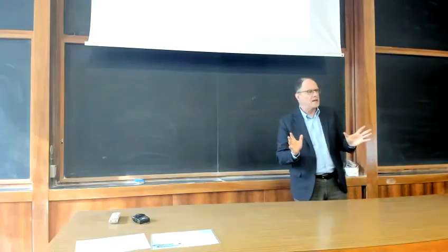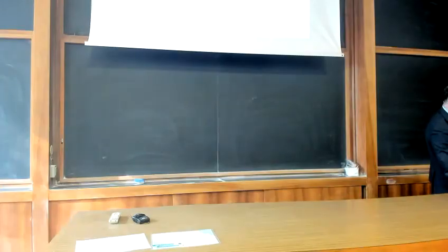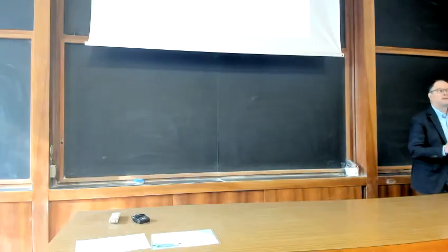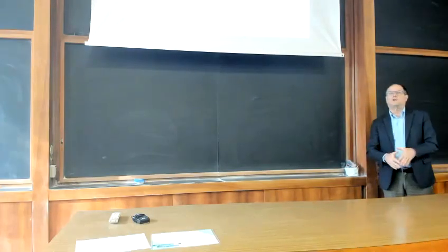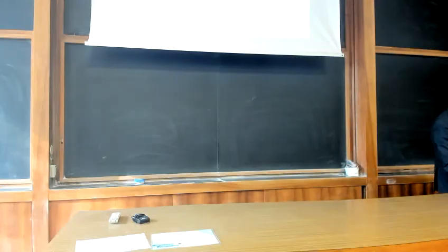We are in sand, for example, and you see the three mechanisms are reported in this chart: general shear failure here, local shear, and punching shear. And on the x-axis, on the horizontal axis, you have the relative density. And in fact, if you remember, we have just mentioned if you have a dense sand, this is general. If you have something intermediate, it's local. If you have a loose sand, this is punching.